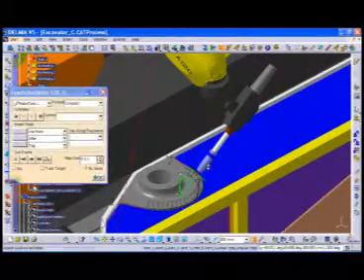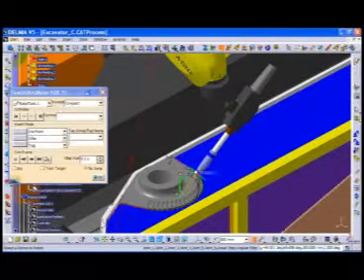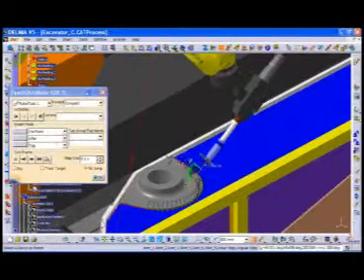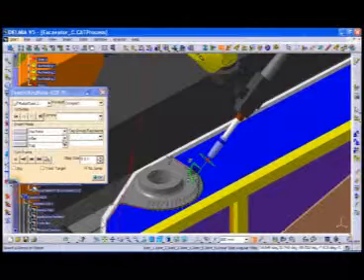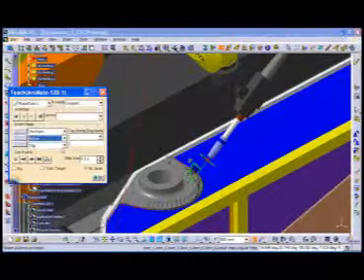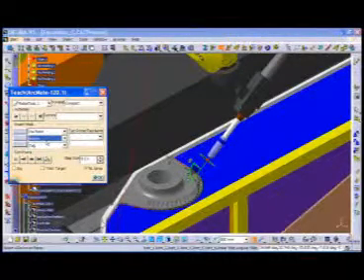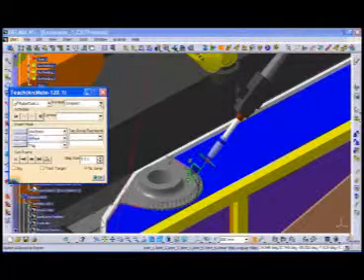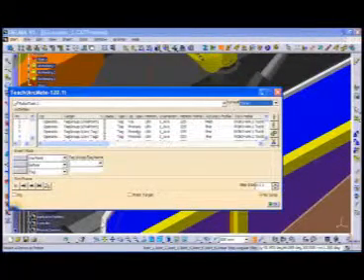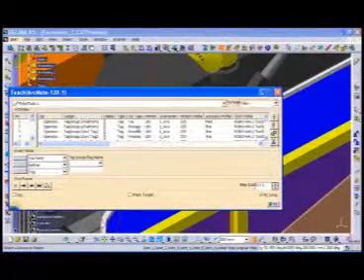The Robot Teach page is where we can manually add robot locations to a robot path. You can insert VIA locations either before or after for ingress and egress to the welds. This is also where we can dress the path with specific robot information for the robot to follow the path.